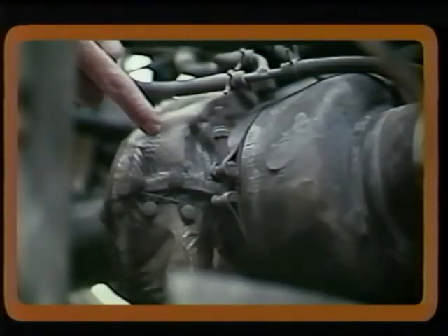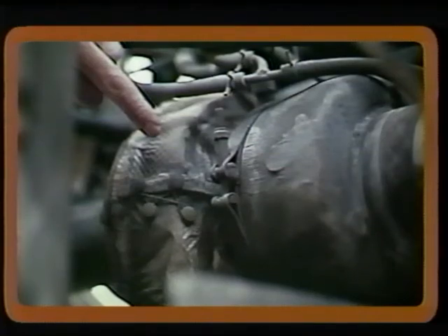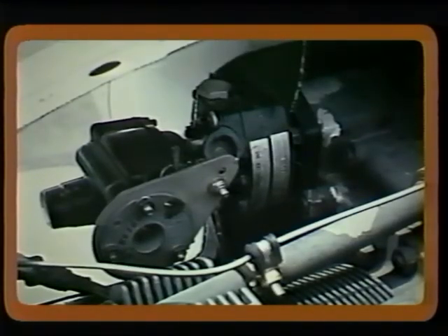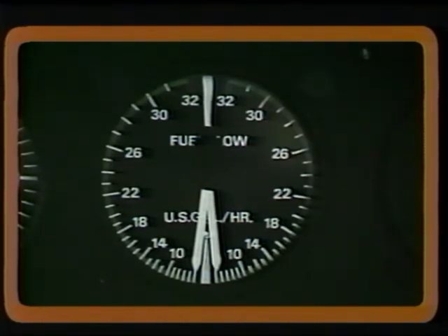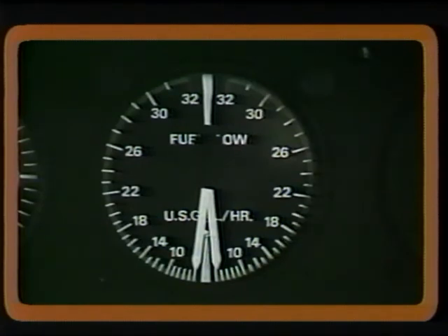The turbocharger must be operating properly, and there must be no leaks in the induction system. The propeller governor must be properly adjusted, and the tachometer must be accurate. Finally, the accuracy of the fuel flow meter, which is actually the metered fuel pressure gauge, should be checked, because trying to calibrate a fuel injection system with inaccurate instruments can lead only to frustration.